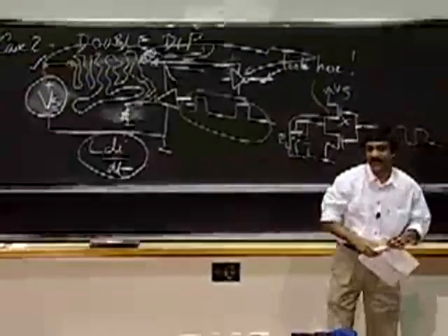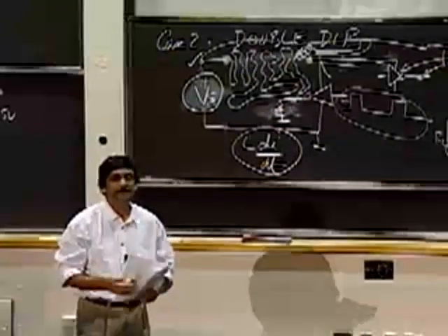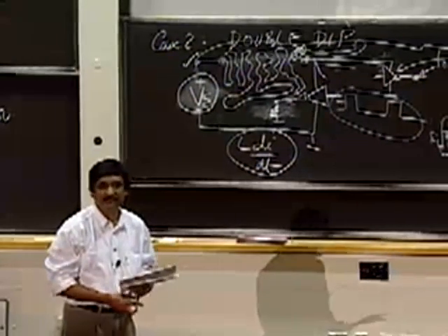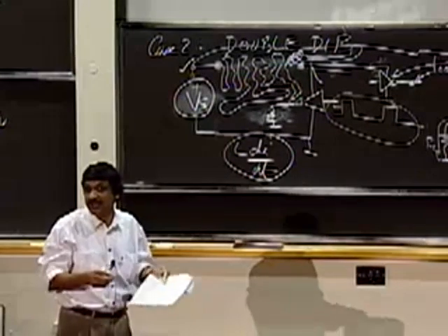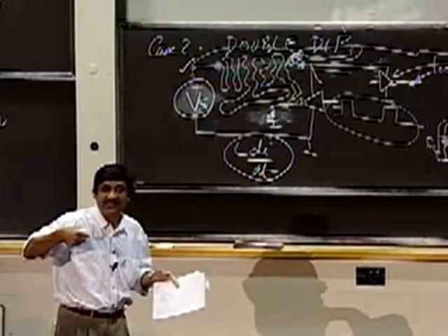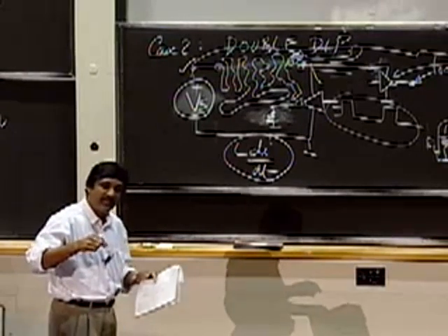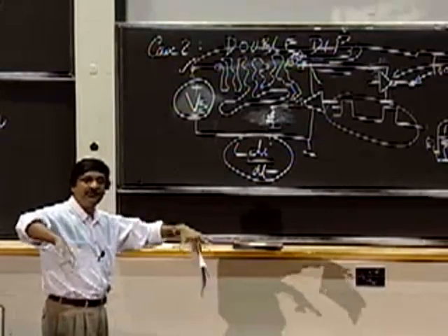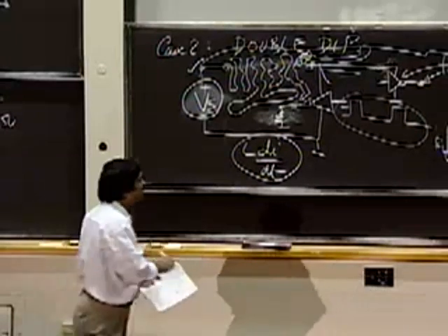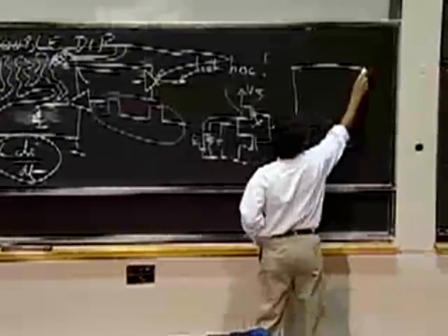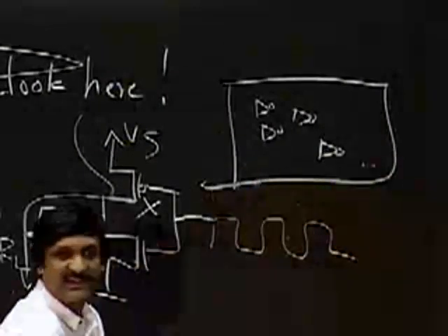In fact, if you build a chip, so we built this chip called RAW in our group, and it has on the order of 10 million gates. We built this chip with IBM's technology, and it turns out that you don't send the power supply in through a pin and then connect that 5 volt or 1.5 volt supply to all your gates. What you do is, from that pin, you build special power supply buffering trees, and each leaf of the tree drives a sub-circuit. In other words, if this is a chip, you have lots and lots of gates throughout your chip.